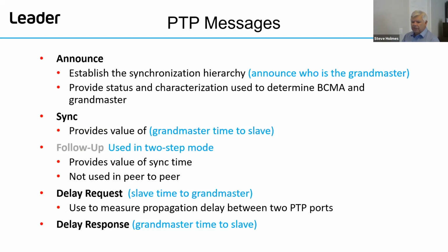So there are several PTP messages to look at: announce messages, sync messages, possibly follow-up messages if you're in two-step mode, and delay request and delay response messages. Now, the announce message is going to go out and say, hey, I am the Grandmaster, here's my priority 1, here's my priority 2, here's my clock class. That's going to set up the BMCA.